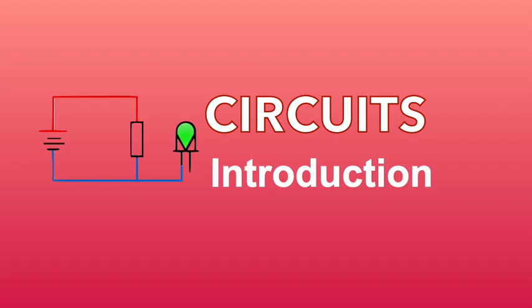This video covers the basics of electrical circuits, including how current flows through a complete loop, and the difference between open and closed circuits. It explains how a battery acts as a power source, how wires carry electricity, and how components like resistors, switches, and LEDs work together. You will also learn how an LED lights up safely using a resistor, why correct polarity matters, and how electricity must travel from the positive terminal of the battery through the circuit and back to the negative terminal. Finally, the video shows how breaking the path creates an open circuit, stopping current and turning the light off.